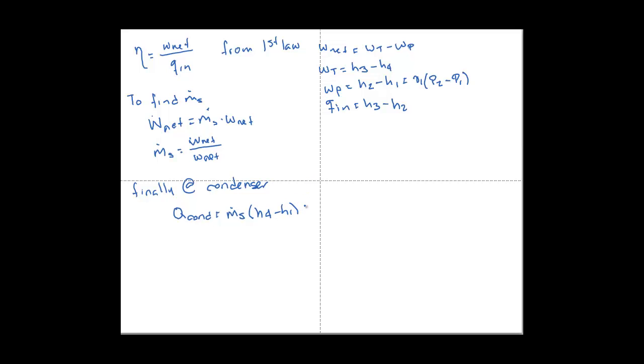That's the steam that is circulating inside the Rankine cycle, and should be exactly the same as the amount of heat that we are returning with the circulating water. That is mass flow rate of cooling water times the CP, the specific heat at constant pressure for water, and delta T.